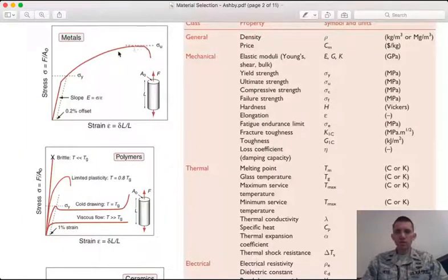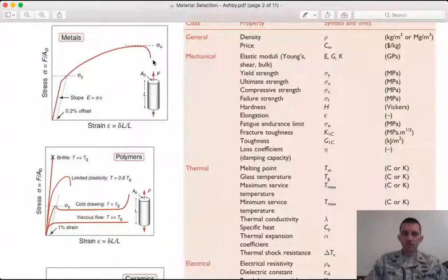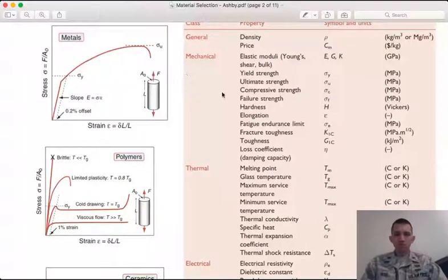Right? Remember, we corrected for this in our homeworks, that it still continues to get stronger until you get fractured, but because I'm not adjusting the area, right, it appears that I have a reduction in stress, but what I really have is a reduction in cross-sectional area there.